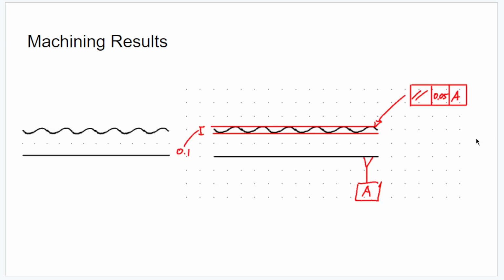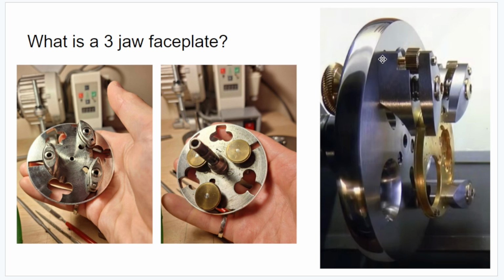So I'm going to be looking at this in terms of parallelism because it's a bit easier to draw. But let's say you had a waviness issue or even some sort of periodic form issue like I did. You could have it where it ends up not meeting your parallelism requirements because of the dips in the surface. But if you remember, in this case, we have a piece that sits on top of it, and waviness is usually quite small.